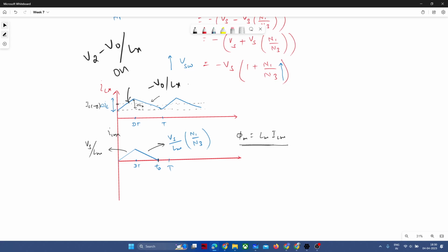Yeah, go ahead, please. With successive cycles, there is a chance of saturation. Yeah, it will come at a certain point. After that, it will enter into the saturation region, right? And once it enters the saturation region, it will start drawing a huge, enormous amount of current. So that we should always avoid.